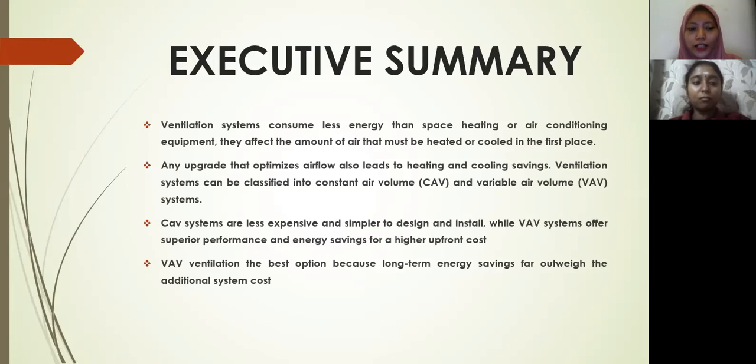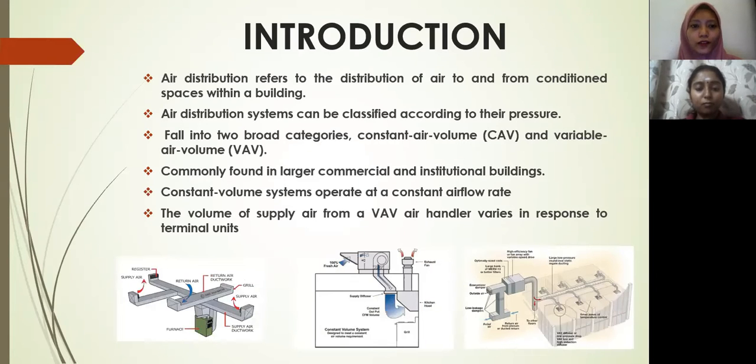VAV ventilation is the best option because long-term energy savings far outweigh the additional system cost. Okay, for the introduction part, air distribution refers to the distribution of air to and from conditioned spaces within a building. Air distribution systems can be classified according to their pressure.